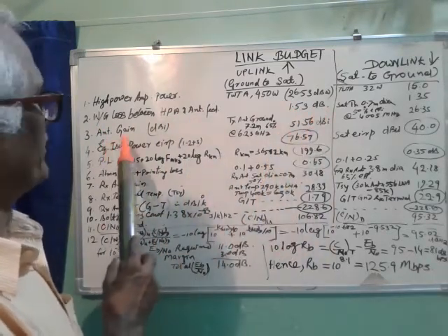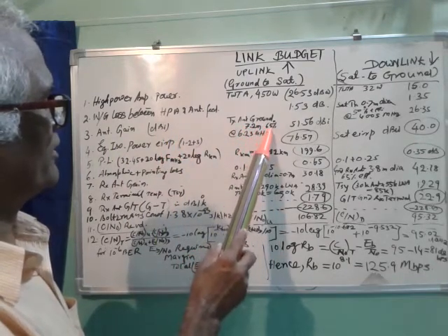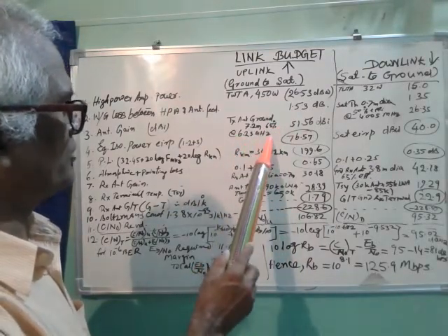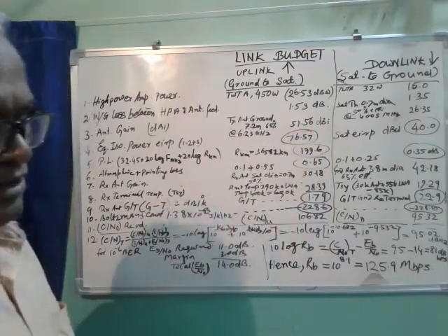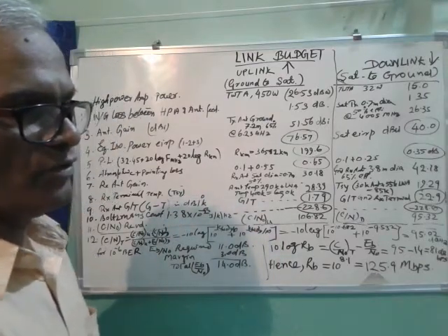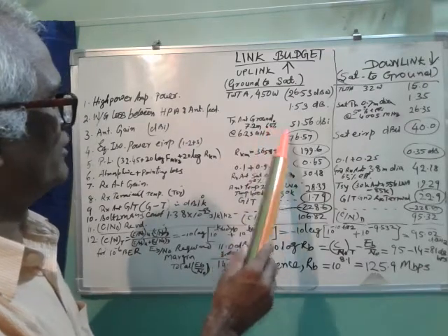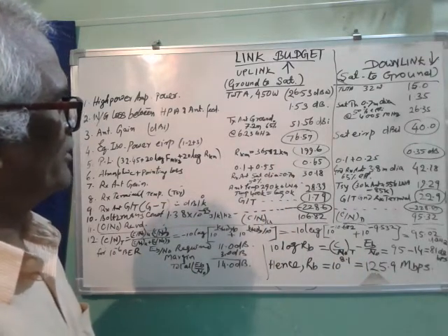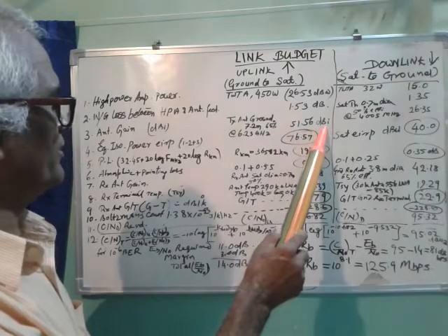And antenna gain, say we consider a 7.2 meter transmit antenna at the ground station, 65% efficiency at C band frequency 6.23 GHz, which will be 51.56 dBi. The formula is 4 pi A by lambda square, or in logarithm 20.4 plus 10 log efficiency, 10 log 0.65, plus 20 log F in gigahertz and D in meters, then we find this 51.56 dBi.